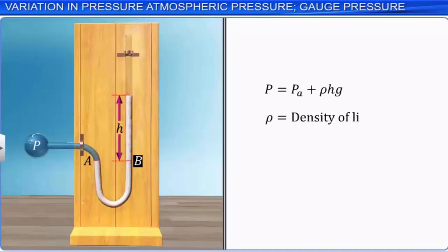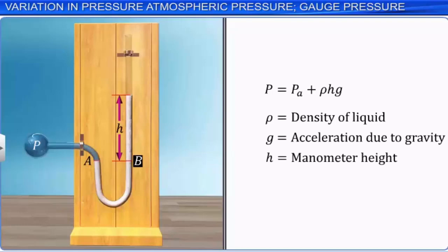For a given change in pressure, the variation in density of a liquid is negligible, whereas for the same change in pressure, the density of a gas varies a lot. This makes liquids largely incompressible. This is why we use only liquids to measure pressure in a manometer.